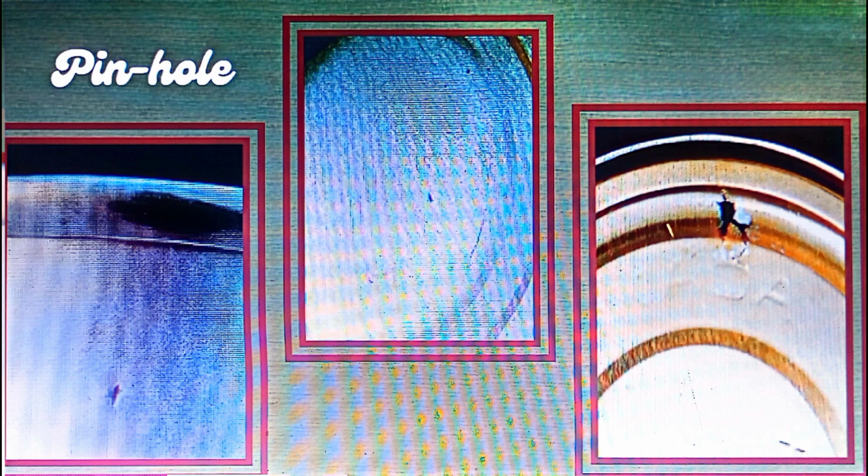The reason or source why this pinhole occurred was due to foreign particles that may be rolled into place during the rolling operation in the mill, especially if they do not bond with the plate. If large particles extend to both surfaces of the plate, a pinhole could be present. Another source of this defect is when the plate was worked during can manufacturing or flexed during retorting, which could lead to the particle popping out, leaving a hole, or a pinhole in the plate.